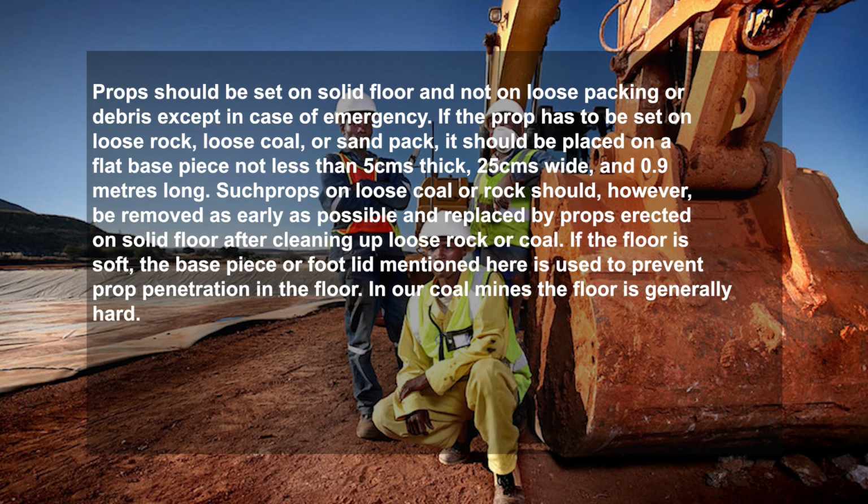If the prop has to be set on loose rock, loose coal or sandpack, it should be placed on a flat base piece not less than 5 centimeters thick, 25 centimeters wide and 0.9 meter long. Such a prop on loose coal or rock should however be removed as early as possible and replaced by a prop erected on solid floor after cleaning up the loose rock or coal.